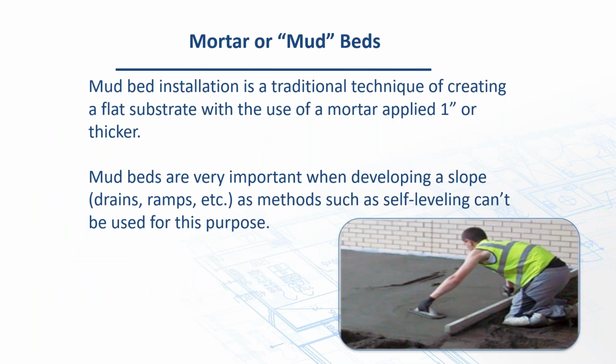Mud bed, excellent solution. Of course, quite frequently, I see a mud bed installation at a fairly consistent thickness, but it may not necessarily be leveling the job unless it's called out to be leveled. In other words, they got 1 1/4 inch, 1.5 inches everywhere, same thickness, but it's conforming to the substrate below it. It may still not be flat enough. It can be. They certainly have the ability to do it. But again, that's just not as common as what we typically see.